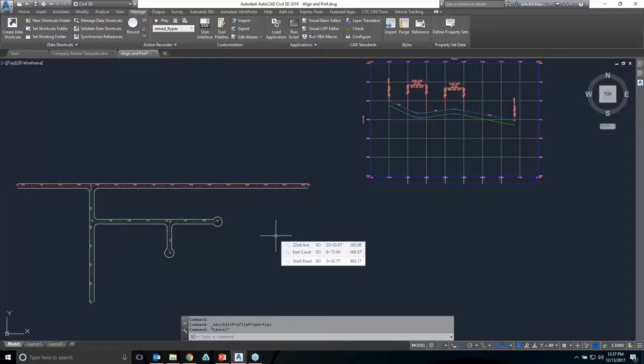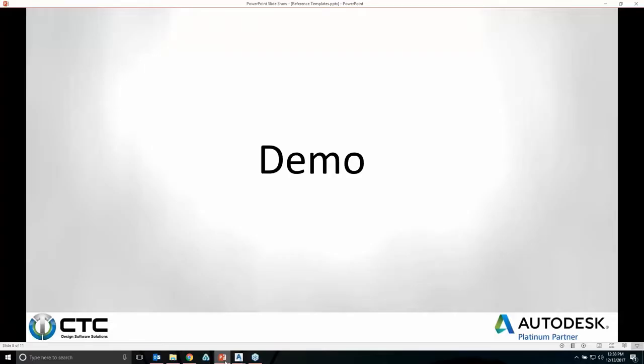You're going to be controlling how many surface styles come in, but you're only going to have one applied to that surface, of course, at a time. So not really going to actually affect large drawings that are large because of the objects that are actually in them. Surfaces being the prime example of that.